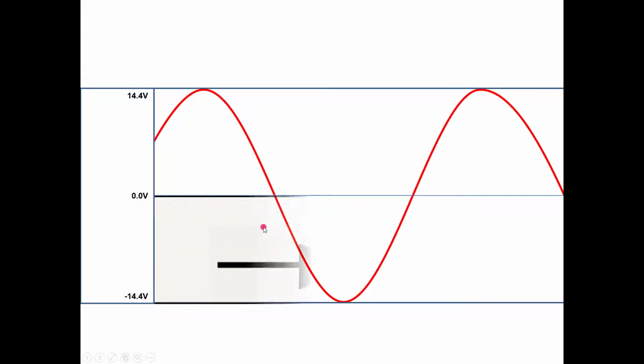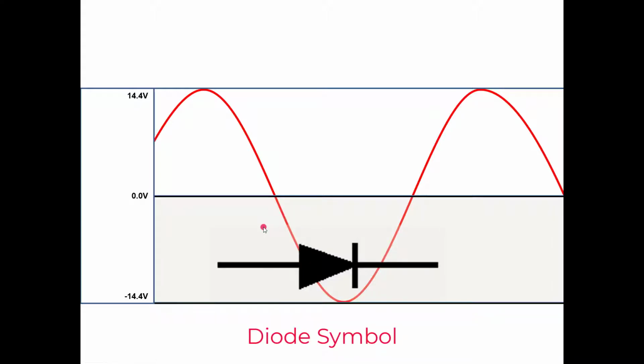So we would force the current to flow into a diode rectifier bridge. There would be essentially one diode here and another diode here. So that would be 2 diodes for this one single phase. Well, imagine if I'm the battery and I've got power coming out and it hits 0, it would be off for a moment. So think of it this way. If I only had one phase, my alternator would be on, off, on, off. That's why we have additional phases to help fill in the gaps.